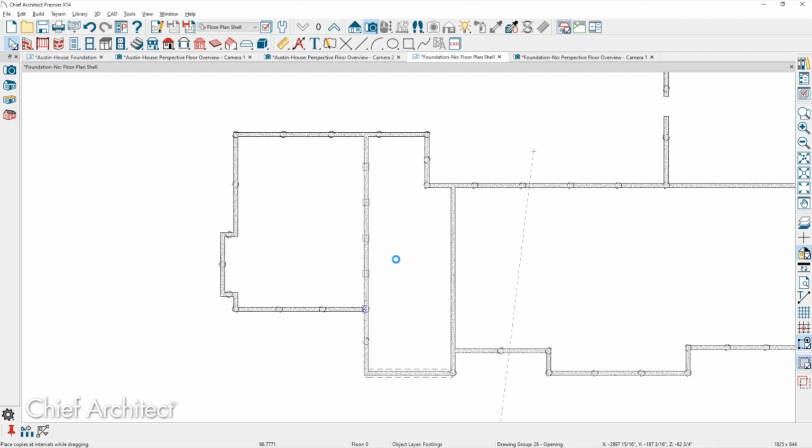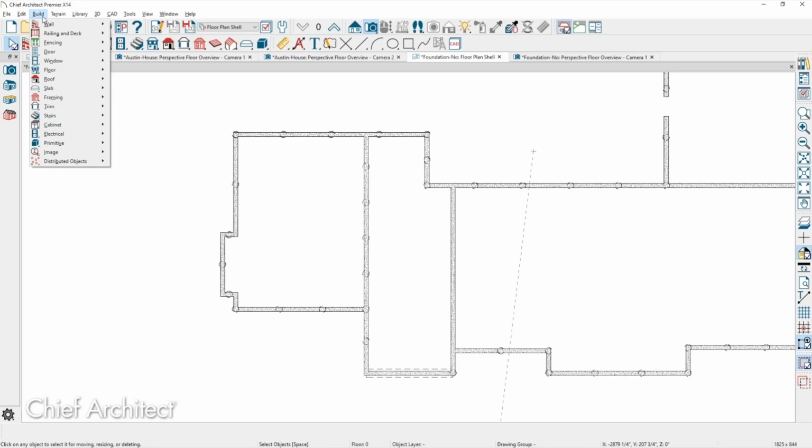Gotcha. Okay, and somebody had a comment they wanted to bring up. Yeah, I was just going to suggest underneath the slab tools under the build menu, there's an option for round piers and square piers. She might try just manually placing those if it's only in a few select areas she needs them. Okay, thank you. So here's what Phil is pointing out.